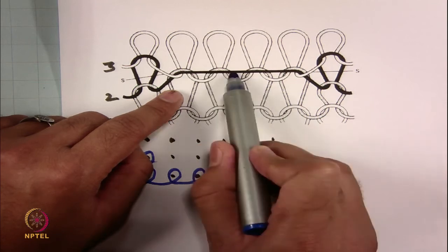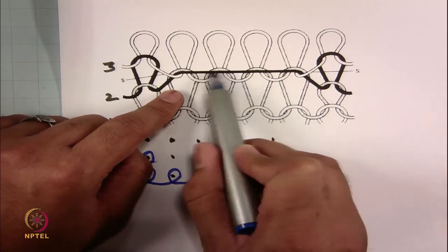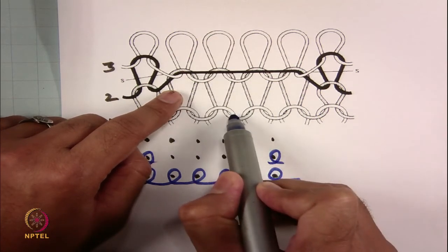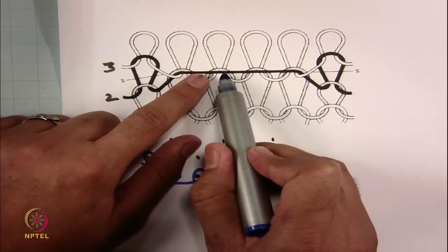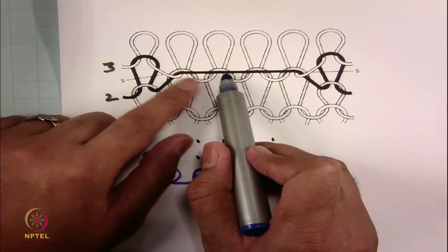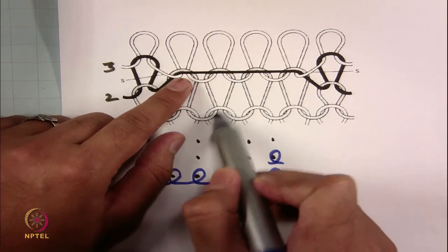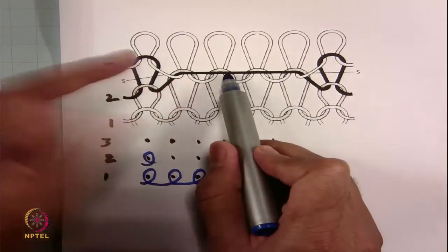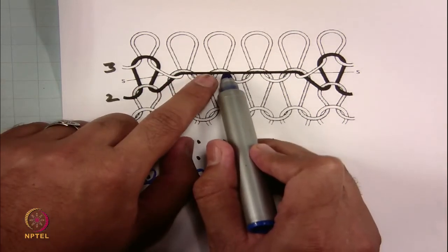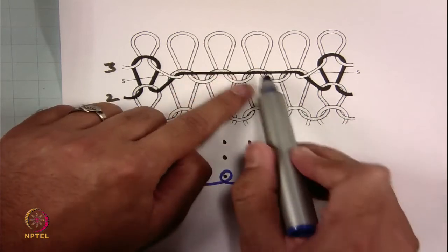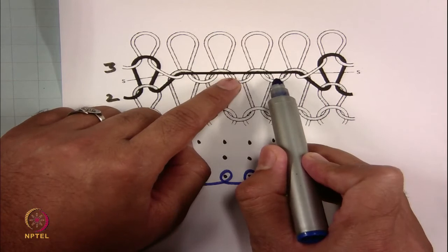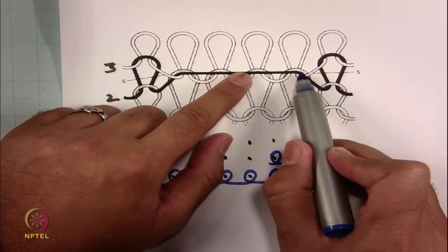So, it looks like float, but since the yarn segment is present on the head part of the old loop, it means ideally on the machine this needle has caught the yarn before clearing the old loop. So, naturally this is the process of tuck. So, we have to represent this as a tuck. Again, if you go for the third, this yarn is caught with the old loop. So, that is why this is also tuck and the fourth one is also tuck.